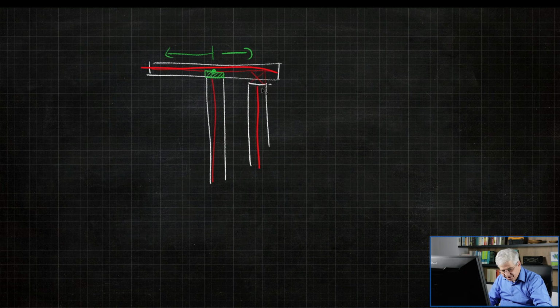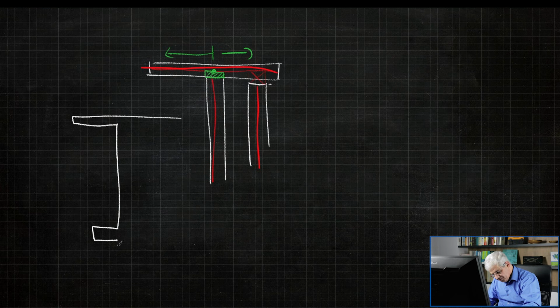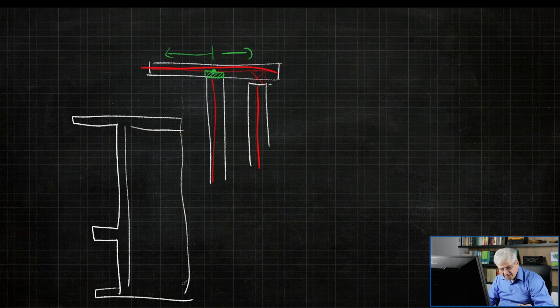And the third one, if you draw the thin wall representation, then you have, let's say this was our cross-section. This was the middle part, and then the bottom. So, and this is the symmetrical axis. Then you should split it. So you at least split in this point and this point, or better here also at the weld. So this is one line, this is one line, this is one line, and this one. So then SCIA Engineer automatically knows this is the C. Don't draw one line here and connect it here.